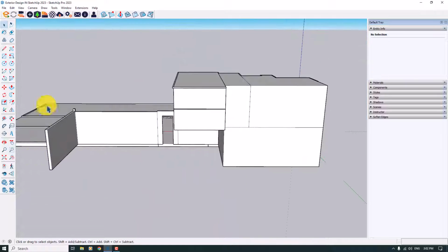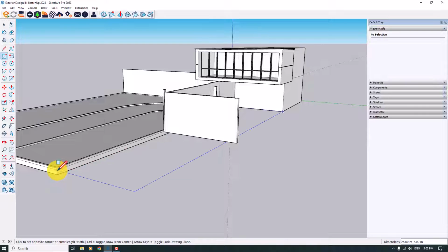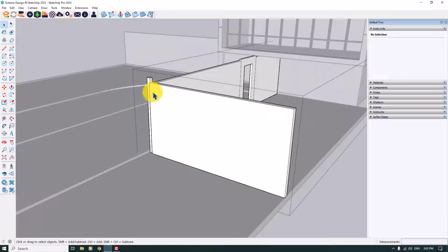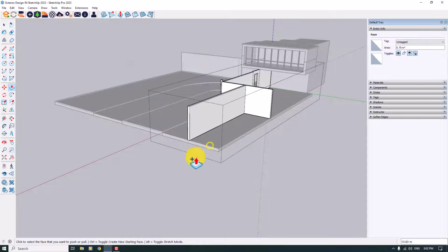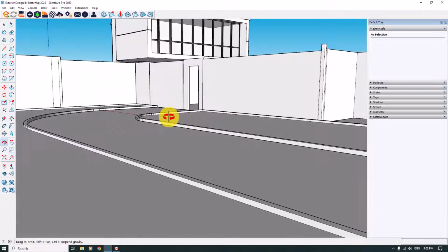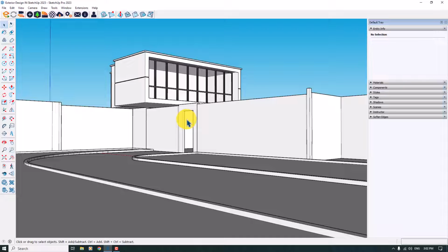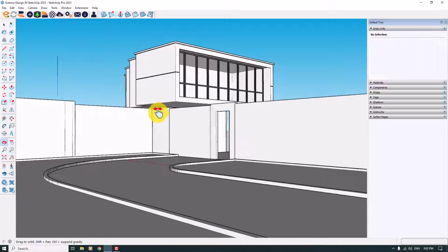Before I do this work, I will generate another area for myself from here to here. Extrude it to the downside and move it to this place. Select it, select this line in here, and take another copy in this place and move it to the 22 centimeter again, and re-export your job like that. When you cover your area, your detailing, rendering, and 3D modeling will be increased immediately. Something like that is really good for our job.